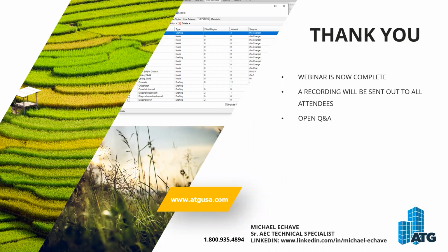Kevin, you asked before you take off, are you still here? Yes, you are. So if it's drawn to one-to-one scale, it is one-to-one. So when it's brought in, that is a one-to-one scale. I could change the scale of the Revit drafting view, but it doesn't change the scale of what was drawn from the AutoCAD, if that makes sense. If it was drawn one-to-one, I import it and I change it to 3/4 of an inch equals a foot, it's not going to change that one-to-one to 3/4. It was still one-to-one before, and you're going to have to scale to 3/4. You can run your dimensions just to verify if you need to.